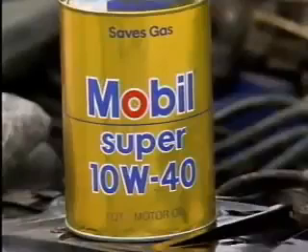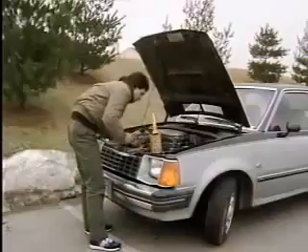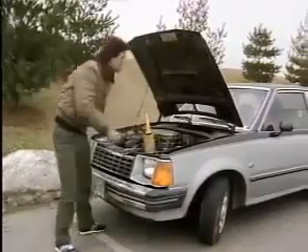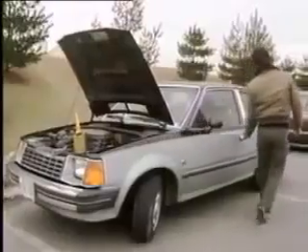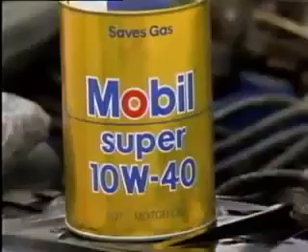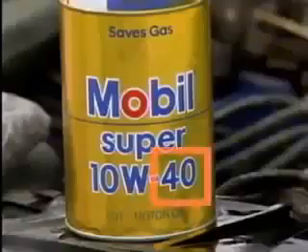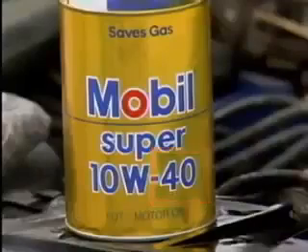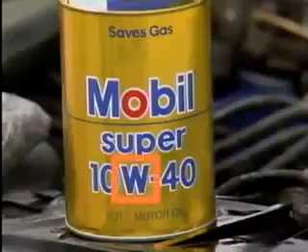Many oils, of course, have to be able to lubricate in both low and high temperatures. For that reason, many oils today are multi-weight. They combine the properties of a lower viscosity oil for low temperatures with those of a higher viscosity oil for high temperatures. A common example is 10W40 oil. At higher temperatures, it will have the properties of a 40-weight oil, and at lower temperatures, it will have the properties of a 10-weight oil. The letter W follows the weight that's associated with lower temperatures. The fact that oil is available in many different viscosities makes it a good lubricant in a wide range of applications.